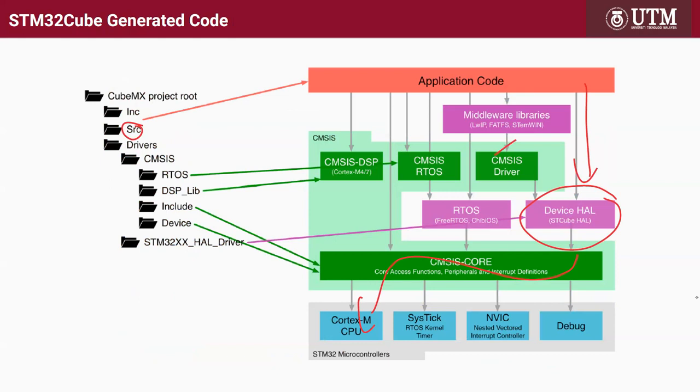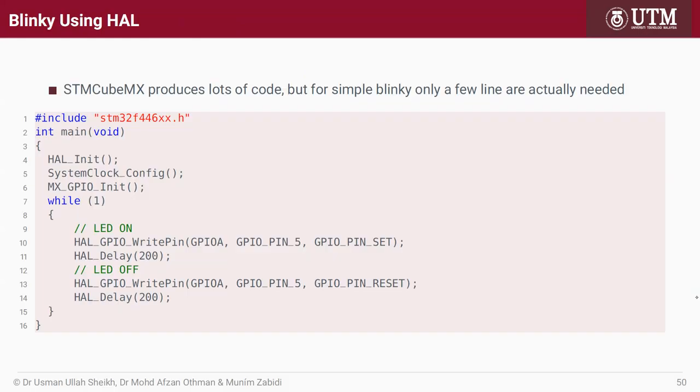But if you want to use a file system, RTOS or DSP, of course you have to make sure they're all linked together. So HAL is on this side. CMSIS is on the left side. The CMSIS green one is ARM, so more stable. The HAL is from ST. So this one is the one that we're talking about regarding stability. Not so sure yet for long term. So this is the mapping of where everything goes through.